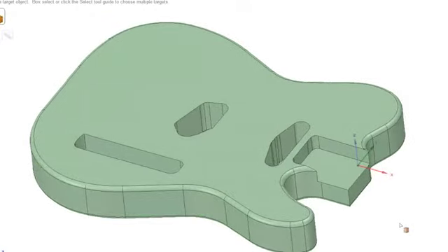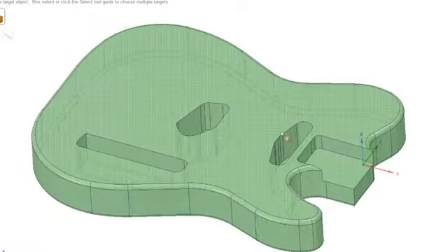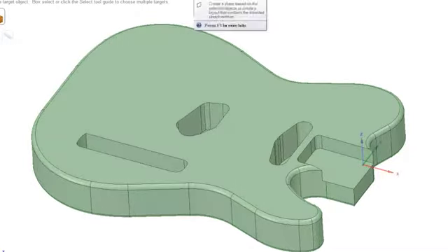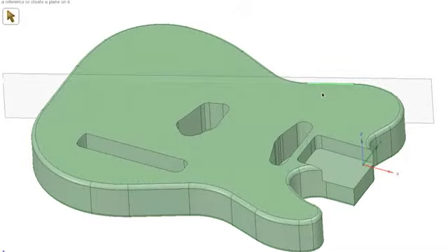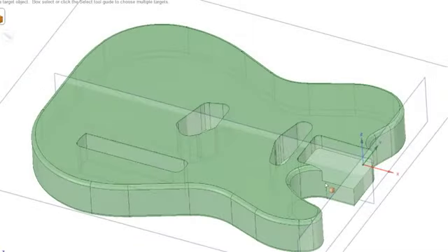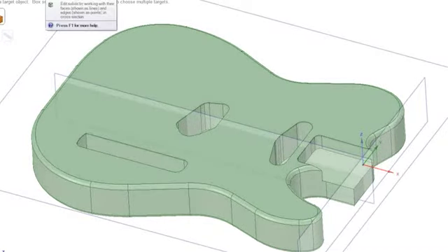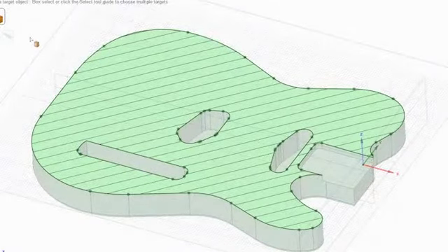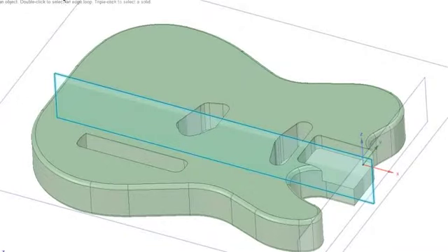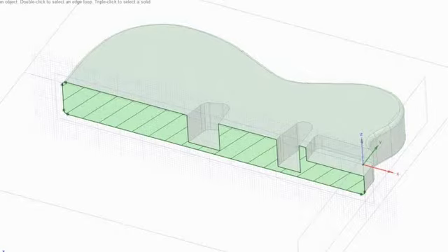So from here, if I wanted to make a couple more edits to the solid, I could create some reference planes. And then maybe I want to edit the depth of those pockets. I can edit it in a cross-section mode. In this case, I'll go ahead and select this center line, go into a cross-section, turn the mesh back on.